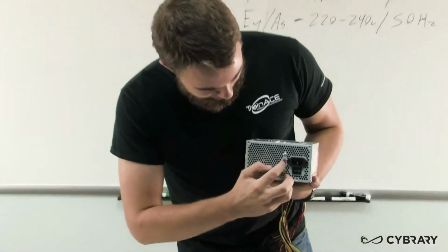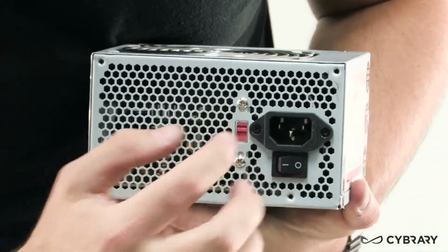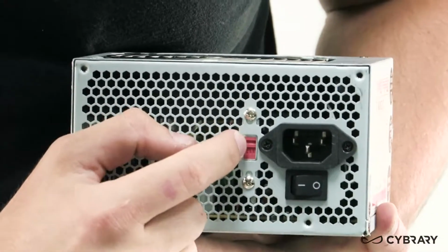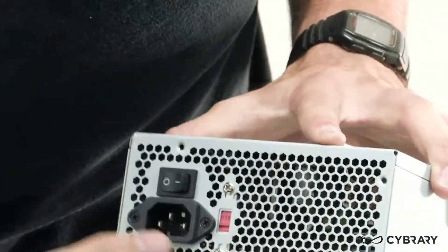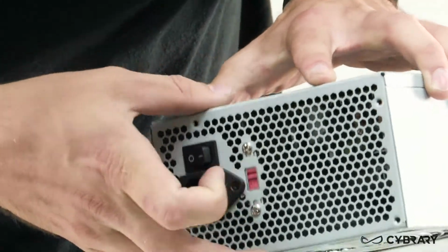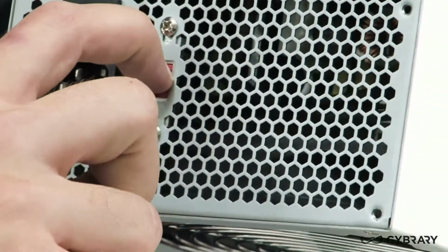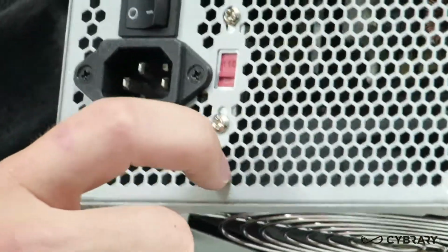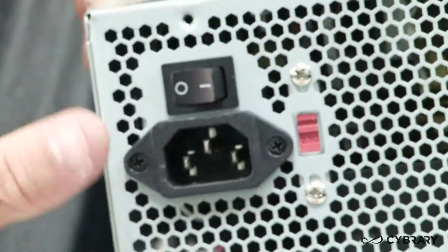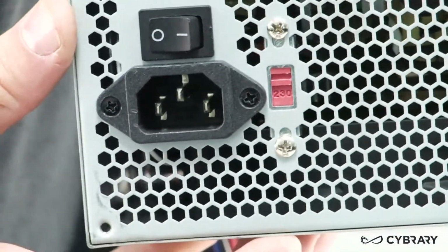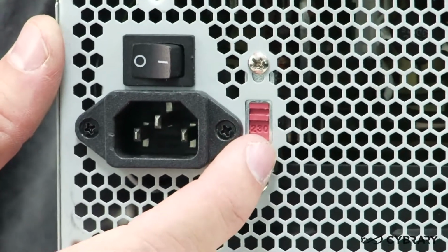So as you can see on the back of our power supply here, which is a part that will be sticking out of the casing for our computer, there is a red switch. On the red switch, we see indicated on this one 115, and when we switch to the other, 230. When we're in North America, United States, we'll want to use that 115 setting, and in Europe or Asia or anywhere that uses 220 or 240 volts, we'll want to switch that setting to the 230 setting.